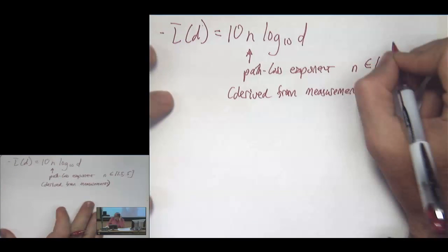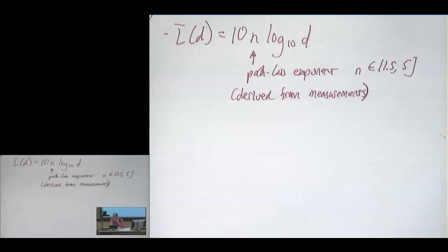It seems like that quantity is kind of innocuous, but there was a huge battle between the CDMA and TDMA when they were coming up with the 3G cellular standard. The expressions for the capacity of CDMA depended very strongly on that path loss exponent. There were claims by the CDMA camp that it was very high, and claims by the TDMA camp that no, it wasn't that high, and so the capacity was lower. So even though it seems like something simple here, tweaking that can have a big impact on system performance.